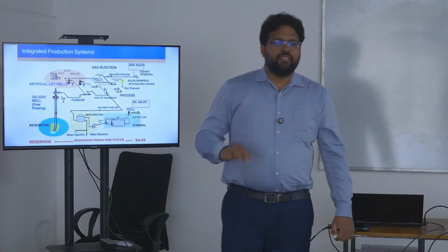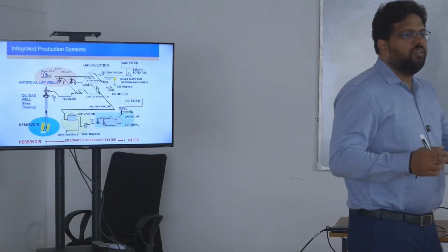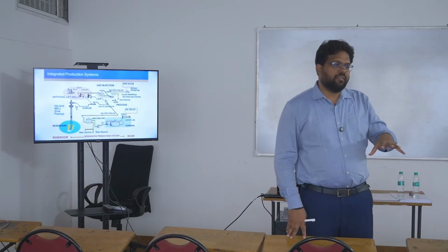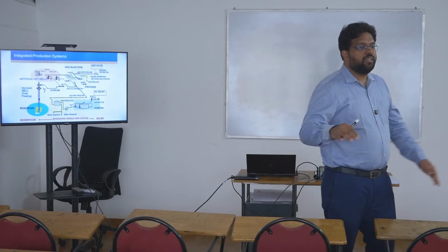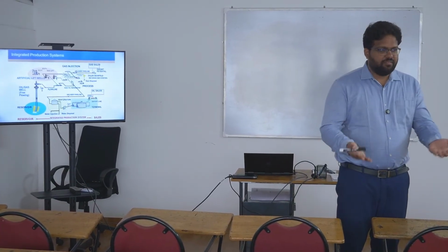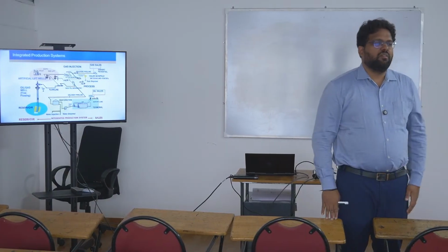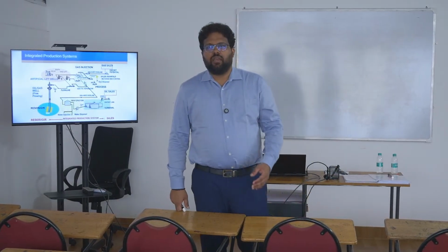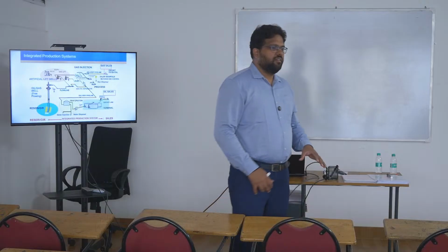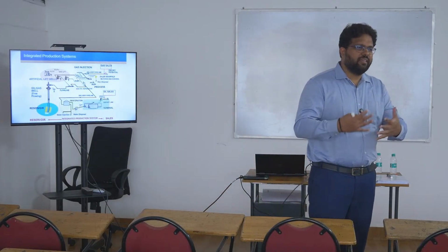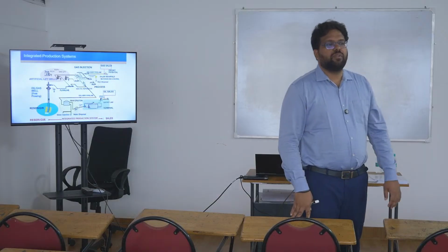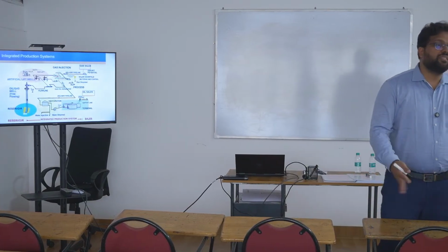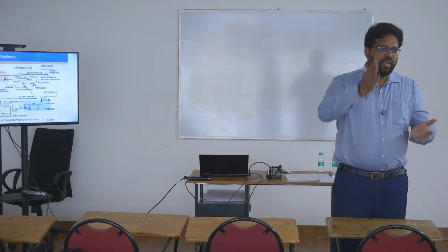But ഇനി നെക്സ്റ്റ് സ്റ്റേജിൽ എന്ത് ചെയ്യാന്ന് വെച്ചാൽ ഈ ഓയിൽ ആൻഡ് വാട്ടറിനെ വേറൊരു ചേംബറിലേക്ക് കൊണ്ടുപോകും. ഓക്കെ, അതിൻ്റെ പേരാണ് ഹീറ്റർ ട്രീറ്റർ. അപ്പോൾ അവിടെ എന്ത് ചെയ്യും? What you will do, you will give heat and then try to separate more oil and water. In certain cases where, എന്താ പറയുക, ഈ ഓയിൽ വാട്ടർ മിക്സ് ആയിട്ട് നിങ്ങൾക്ക് ഇതിനെ തീരെ സെപ്പറേറ്റ് ചെയ്യാൻ പറ്റുന്നില്ല എന്നുള്ളൊരവസ്ഥ വരുമ്പം, what you will do, you will add some chemicals. ഡീ ഇമൾസിഫയർ, അതായത് ഒരു എമൽഷനെ ബ്രേക്ക് ചെയ്യുക.